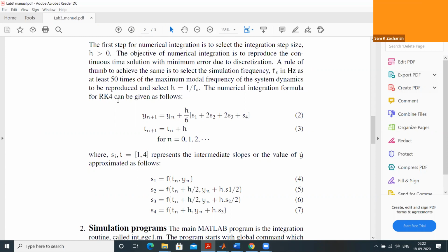This should not be confused with other critical frequencies associated with control systems. One frequency, some of you may be aware, is the sampling frequency with respect to communication. If you are sampling some particular signal, the minimum sampling frequency without losing the message content is twice the message frequency.